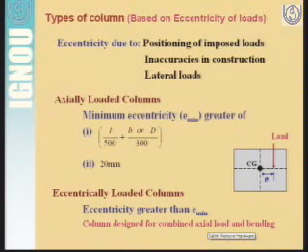What you can do is solve the problems given in your course material by replacing that M15 grade with M20, and redo those solved problems. Then you will get confidence in designing various types of structures. So you can follow the new code and simply replace M15 by M20 and take the characteristics of M20 concrete while solving the problems.